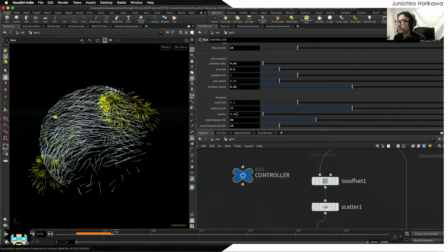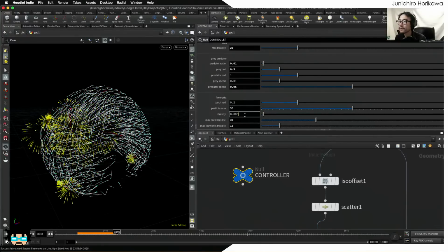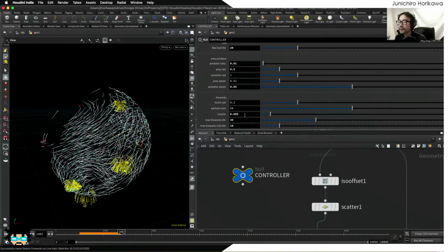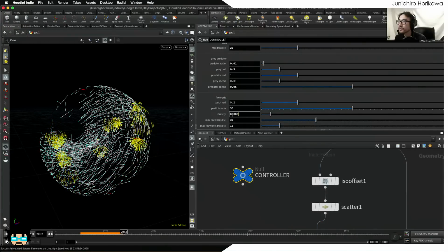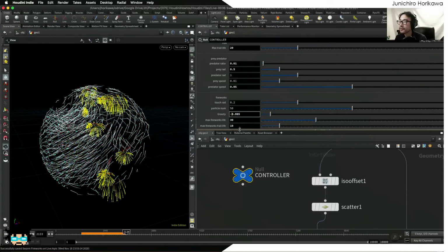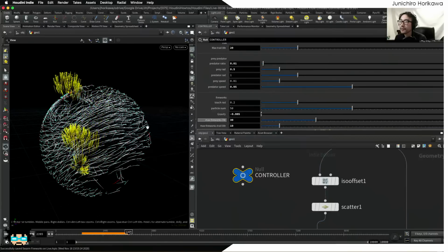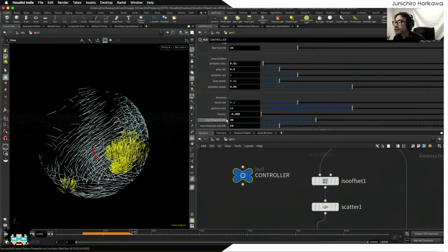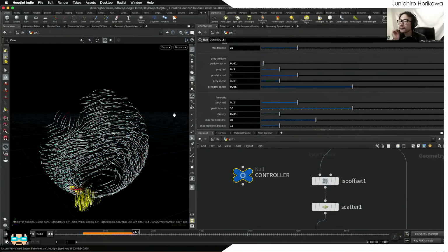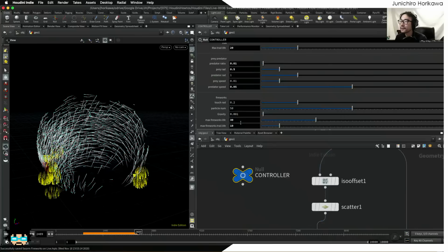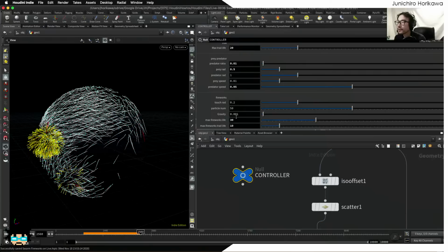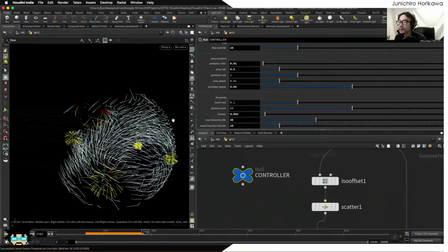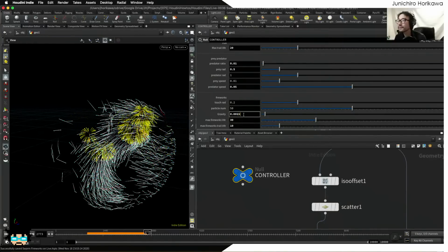If I increase the value for the gravity, like set it to 0.5, you see more particles going downward. You could also do that in a negative direction by setting it to negative, creating upward fireworks, which is unreal but interesting. Alright, that's too much. Somewhere around 0.002 is good, I guess, or 1.5.